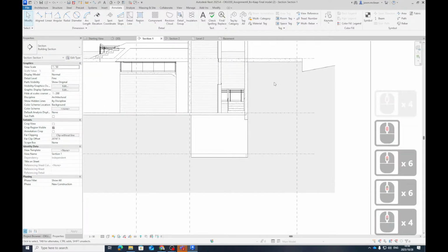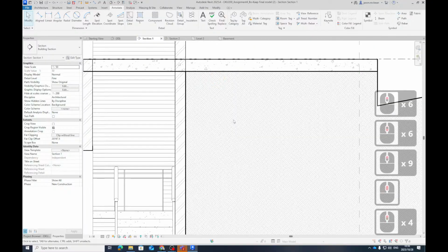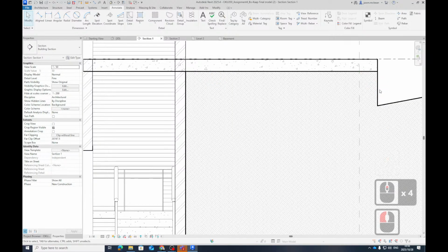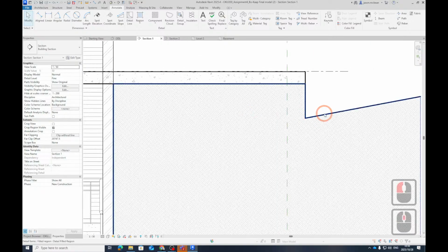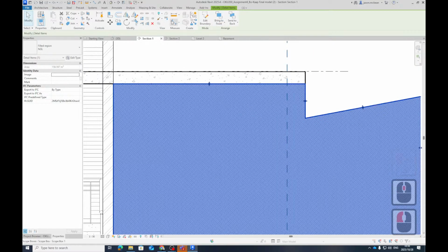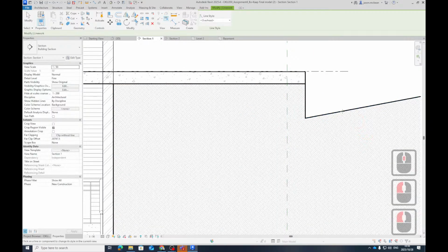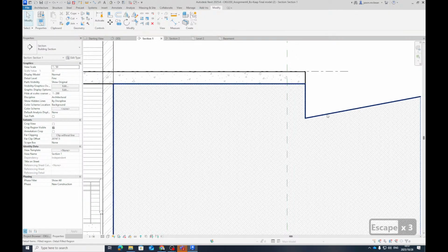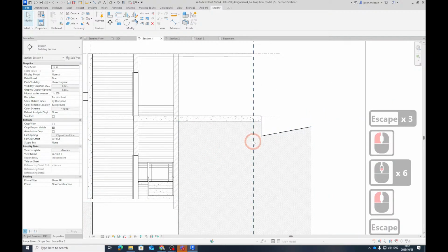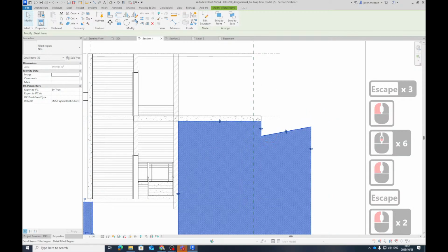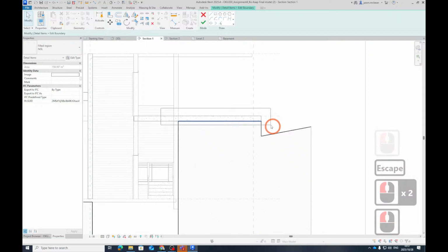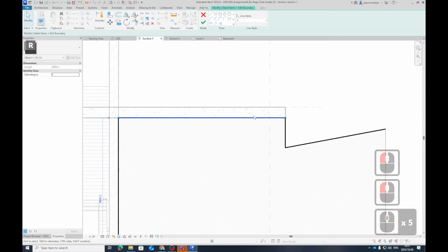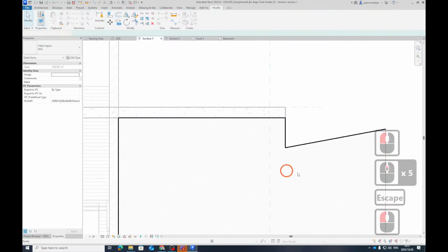But remember, this line work must match whatever it abuts to, because if it doesn't, you get this weird look. But Revit's got one last little trick you can do. You can overwrite line work for a certain bit of line, or for certain objects. You see that? But it doesn't do it with fills because it's a detail item. So it's just a weird thing. But just remember, if you go and edit, make sure that this line weight matches the line work that it's connecting to. Then it looks correct.